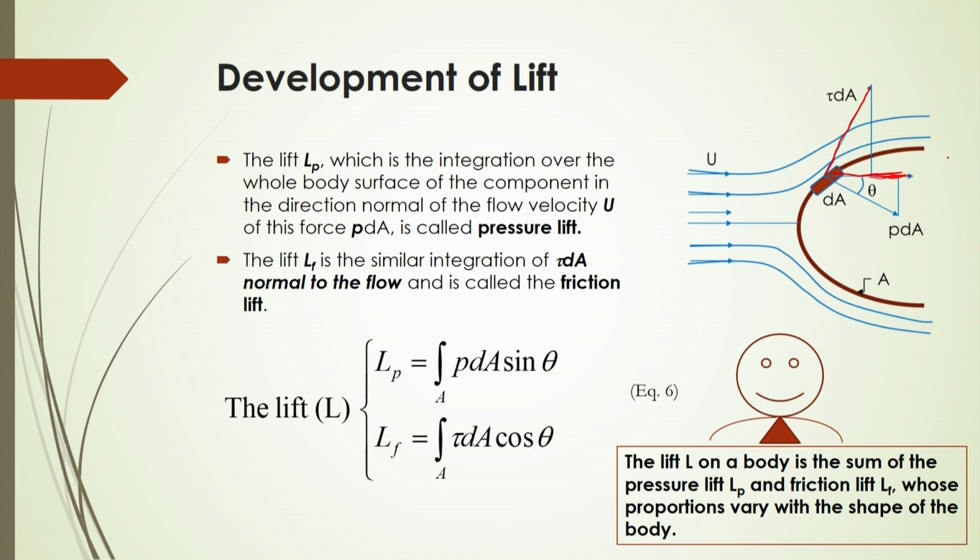But here, if we consider this shear stress component in the normal direction, then it will be cos theta, and these components will be regarded as lift force because of this shear stress. And for this pressure component in this direction, it will also be regarded as lift force due to the pressure force. So, the total lift force will be the summation of this L_F and L_P.